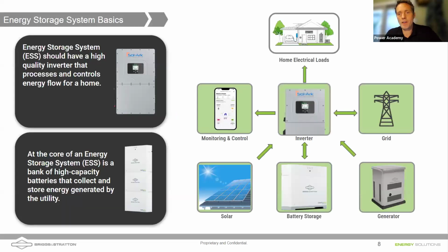So we often start here with the basics. And Daniel, I'll let you introduce this slide. What are we looking at here? Of course, we're looking at the basics of an energy storage system. In the context of this training, the key is to understand that we DC couple a lot through the solar. It has its own built-in MPPTs, and we'll talk in a minute exactly what an MPPT is. Solar produces DC. We feed that DC through the charge controllers and charge up the batteries. And only when we need to use the DC to turn it into AC do we use that solar converter to power the home loads.